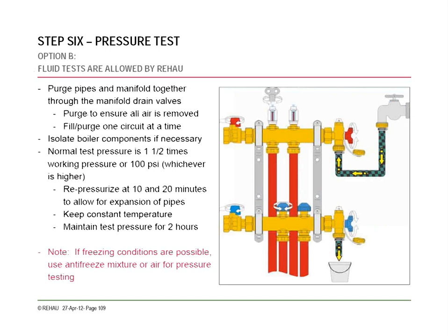You can also fluid test. You're going to want to go through and purge each of your tubes once the system is getting filled anyway. But you can do this to pressurize it before the slab is poured if you want. This is just showing you can go through and isolate each of the loops, purge all the air out, go one by one, and then go ahead and open the whole thing up and keep filling.